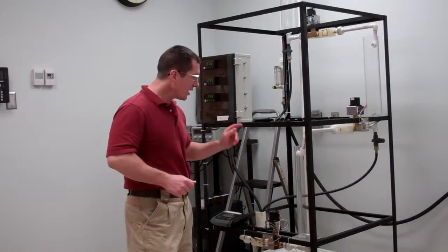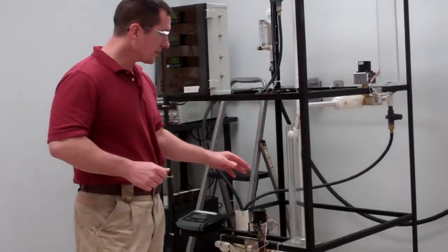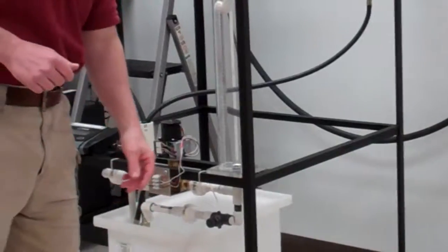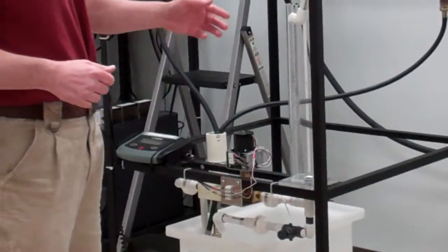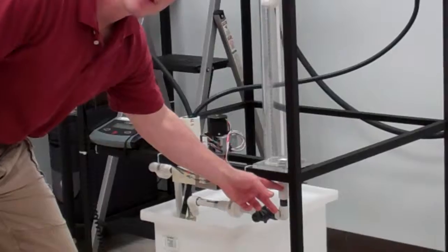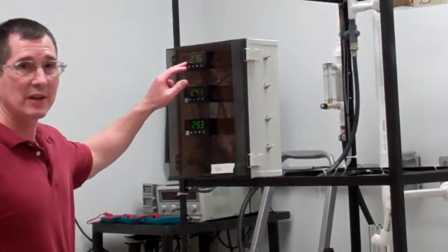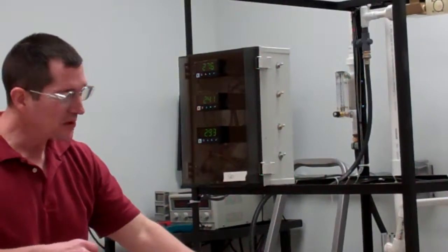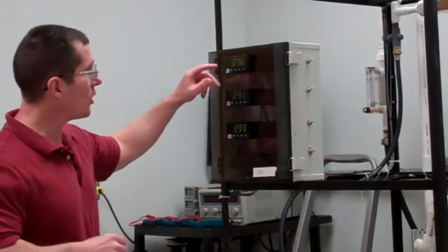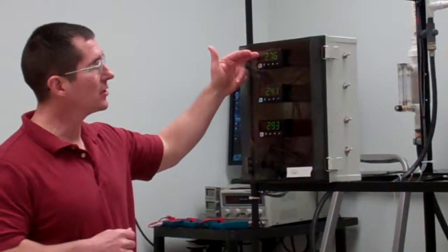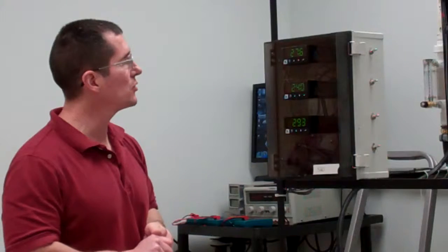But one of the most important parts of this experiment is going to be the characterization of the input measurement sensor. So we have a differential pressure transducer. It's mounted at the bottom of each one of these tanks. And it's going to send the signal to the controller. Now that signal, the output signal from the sensor, is the input signal to the controller. And this controller is set up to read, display units in counts. So it's not like an engineering unit like you'd be used to.